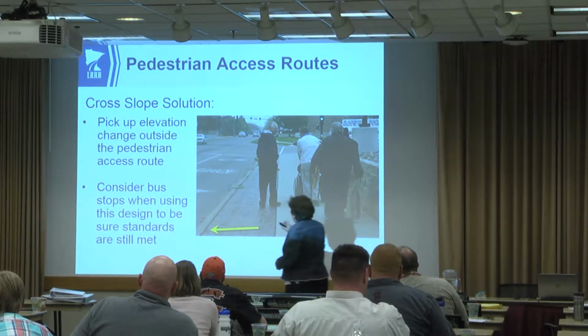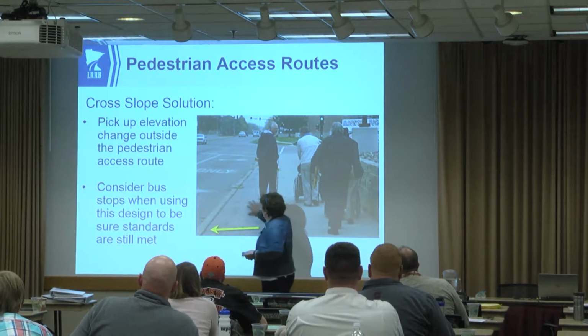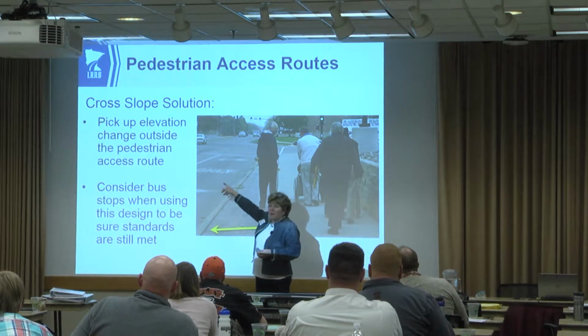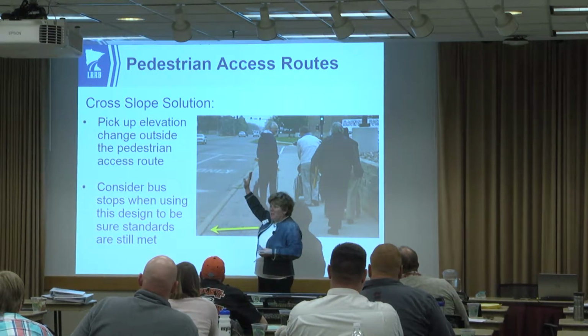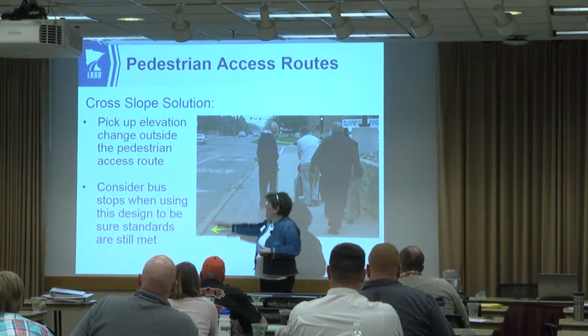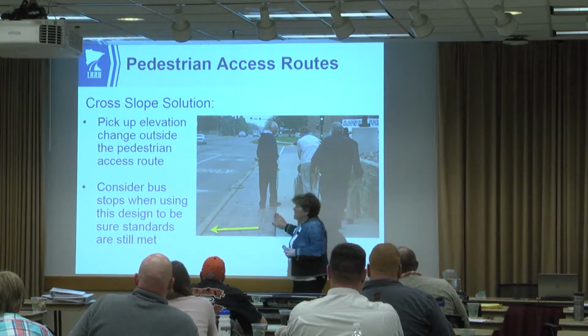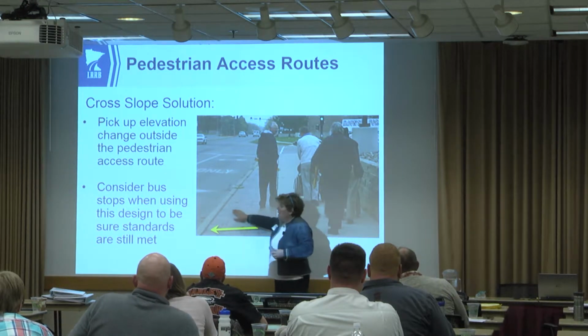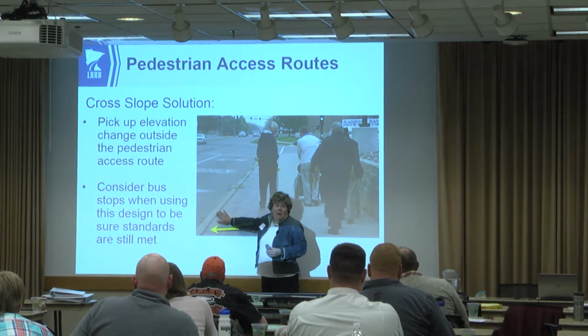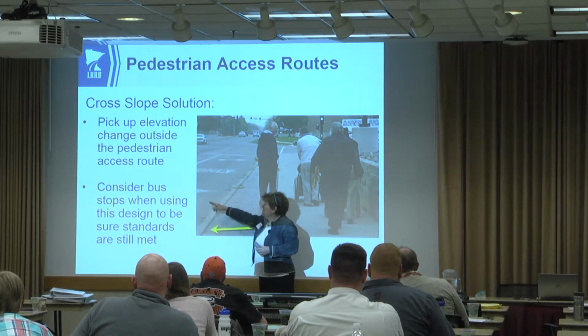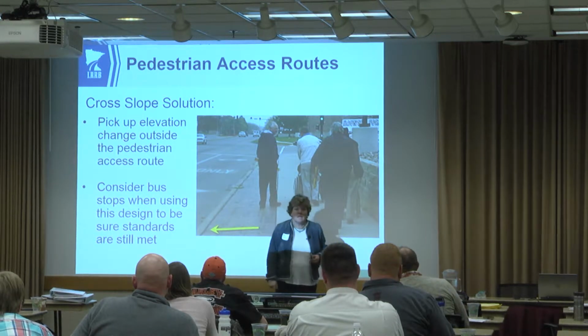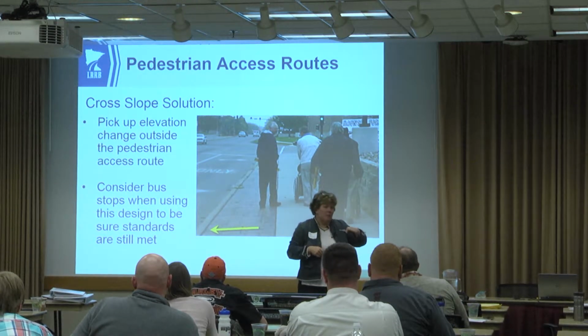I teach highway design here at the university. The way we lay out these grades is usually controlled by the profile of the road. When you get into an intersection, then you got all kinds of weird things that start happening. But let's say in between the block, you can use this space between the edge of sidewalk and the top of curb to accomplish that change in cross slope if needed. So sometimes you don't have much latitude with your typical section, and so you end up with an elevation at top of curb that is pretty much fixed.